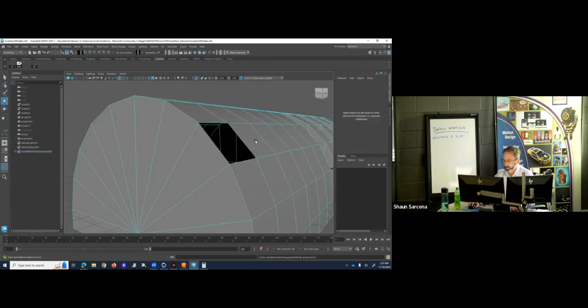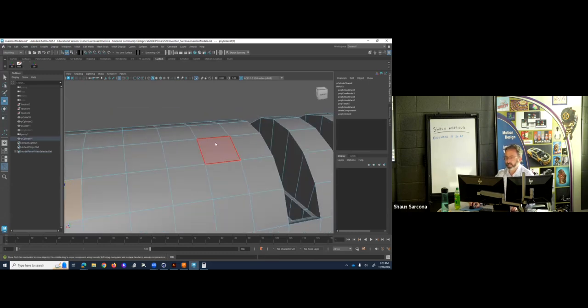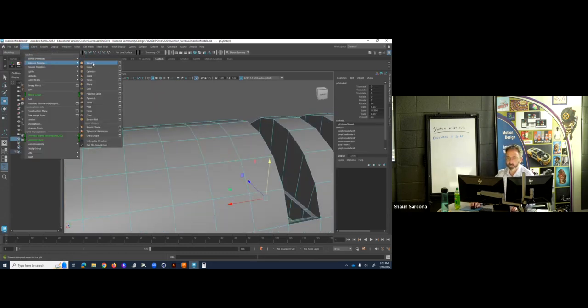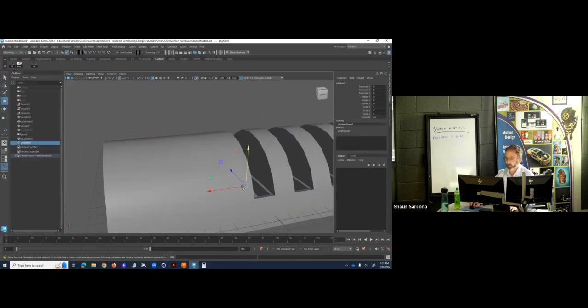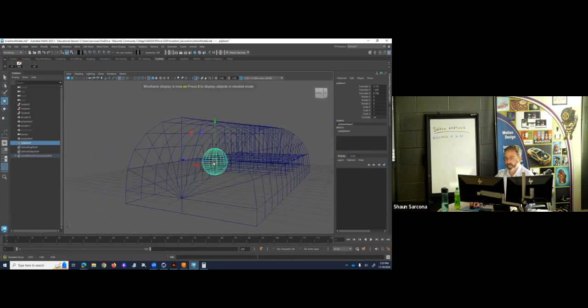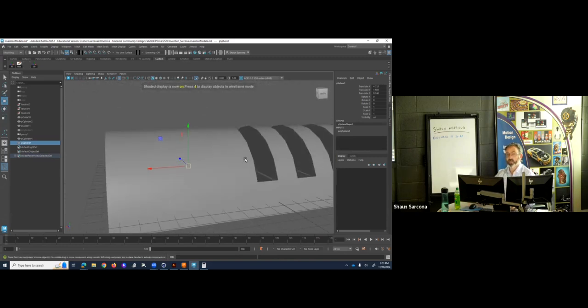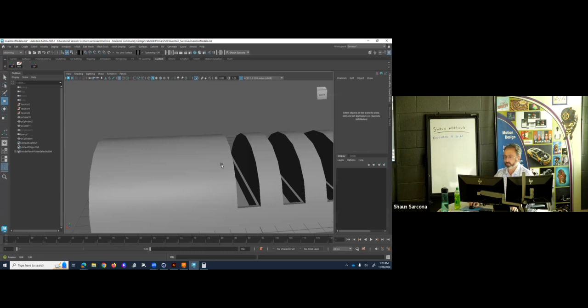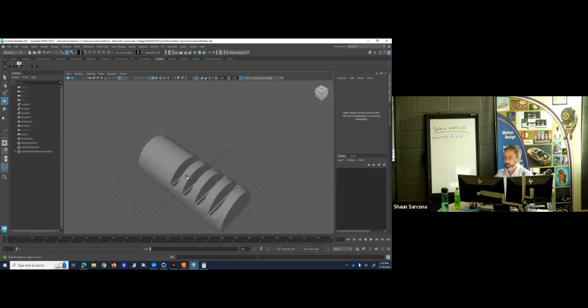Let's say you had some surface on the inside and you didn't realize it, like, oops, I have this sphere kind of sitting on the inside. It'll actually print that sphere on the inside. It'll make the entire thing solid, and then it'll look horrible. Okay, it'll be like 10 pounds. It'll be very wasteful. So think about those kinds of things as you're building your stuff. Questions?